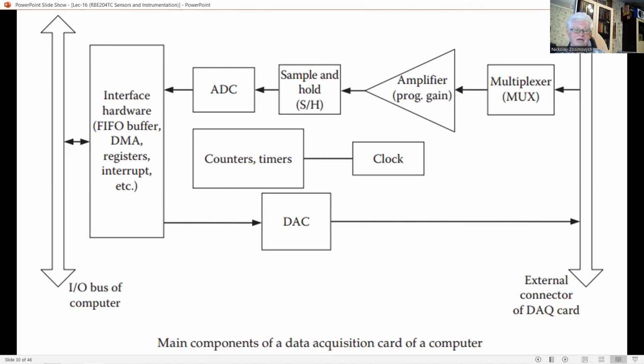On the other hand, a digital output from a computer has to be converted into the analog form using a DAC, for feeding into an analog device, such as a drive amplifier, actuator, or analog recorder, or maybe even a display. So DAC, ADC, and MUX are studied in this section. Both ADC and DAC are components in a typical DAQ card, sometimes called an input-output board.